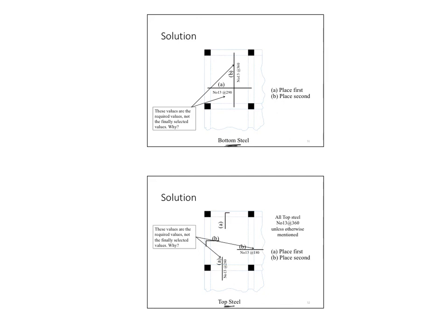And a lot of times we even unify, so for both of them we would just pick one number and go with it. The same thing applies here. The 18 centimeters and the 26 centimeters are not practical numbers. More practical numbers are those that go with 5 centimeter increments. So you go 15, 20, 25 centimeters, and so forth.